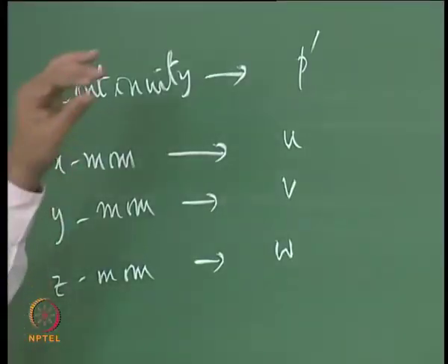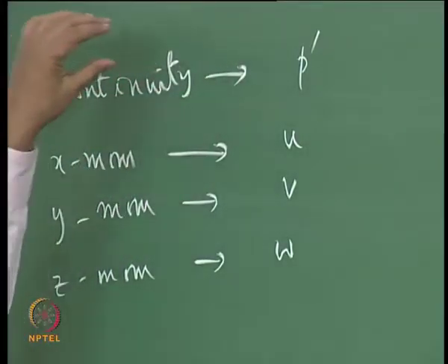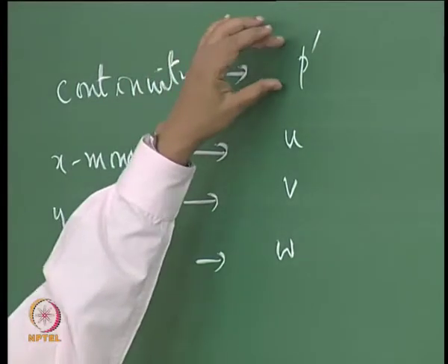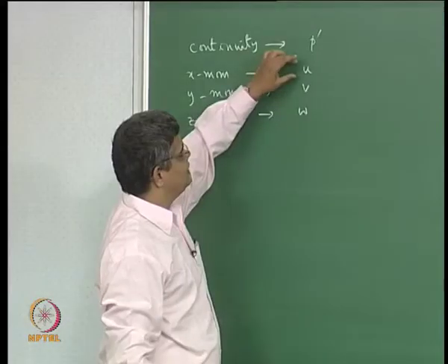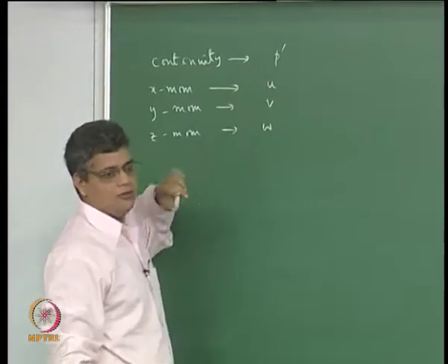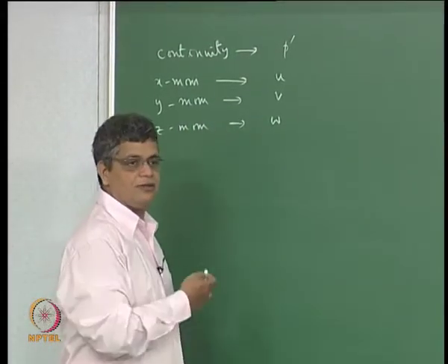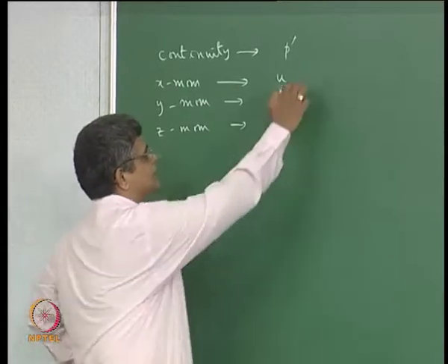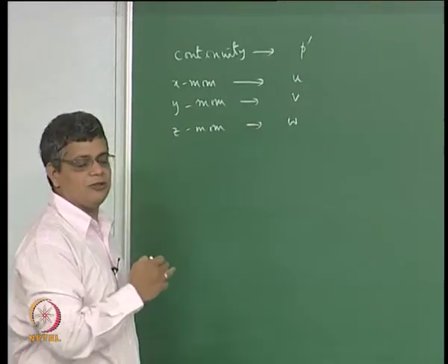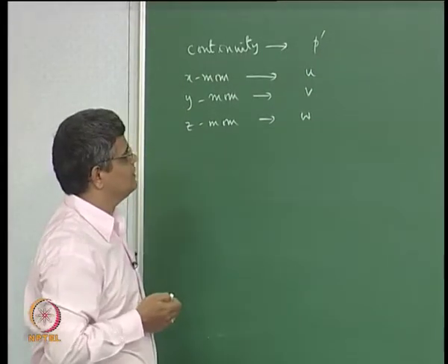Now we have the corresponding form of conservation equation which will give us the pressure correction and u, v and w at the appropriate points, and we note that we have made use of the staggered grid approach and the form of the pressure correction that we have already described.